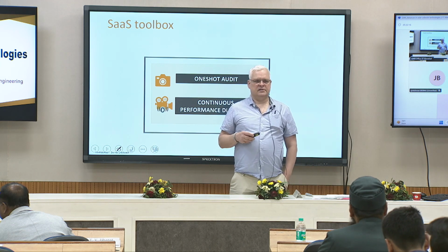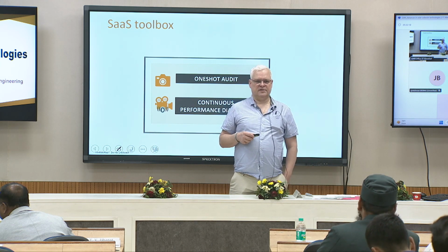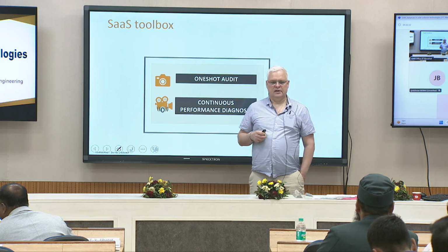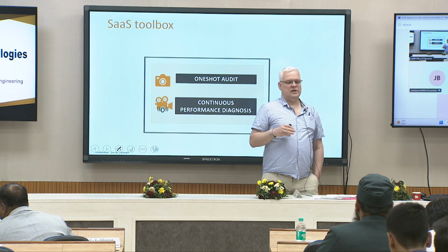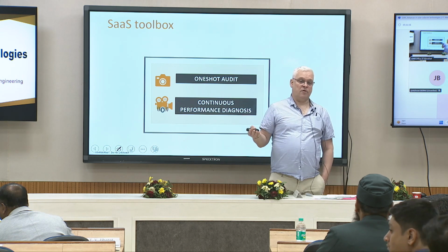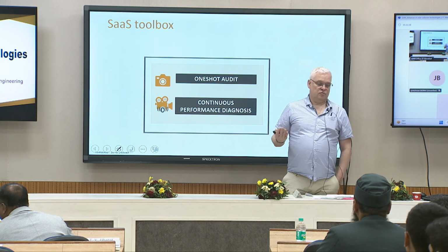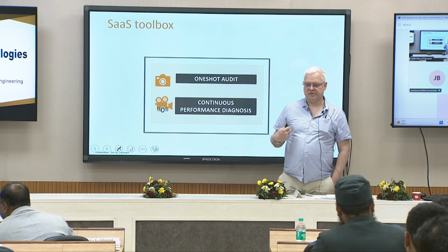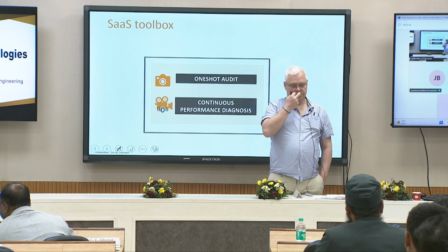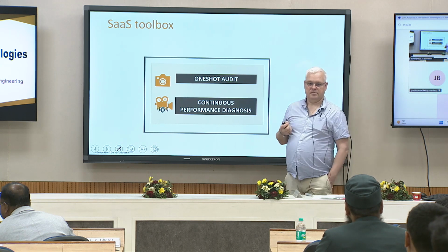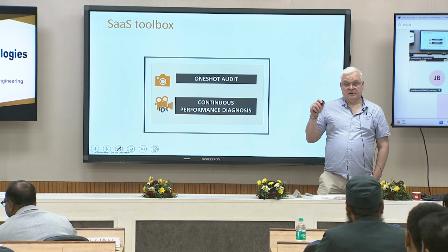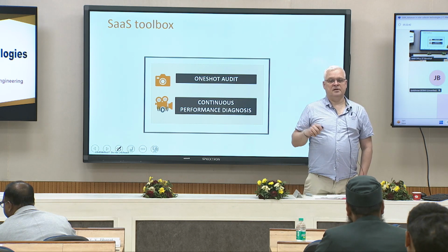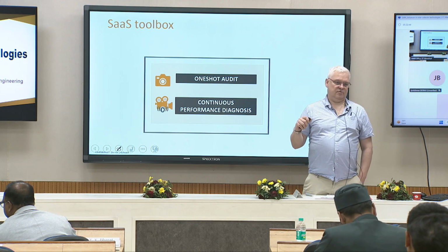It was 80%, 0.8, okay? If the performance ratio is at 80% or more, that's good, no problem. If it is under 80%, that's not so good. There is a problem. The problem could be since the beginning, because the PV has not been well integrated.